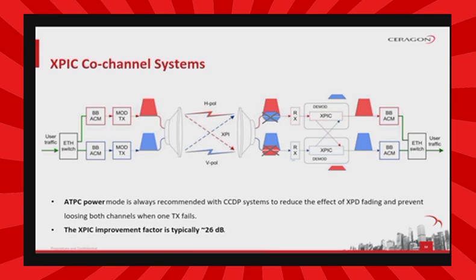The following figure is a basic graphic representation of how the signals involved in this process are sent, interfere with one another and get extracted at the receiver end, to obtain the double capacity possible. The H plus V signal is the combination of the desired horizontal signal and the interfering vertical signal, marked in lowercase, to denote that it is the interfering signal. The same happens with the vertical signal reception and the horizontal interfering one.